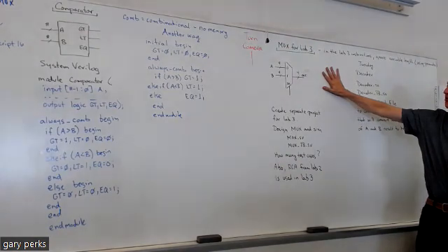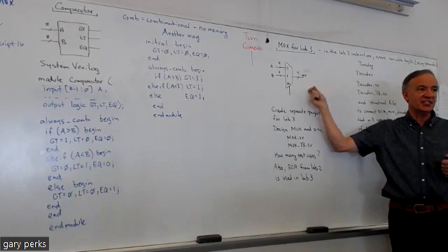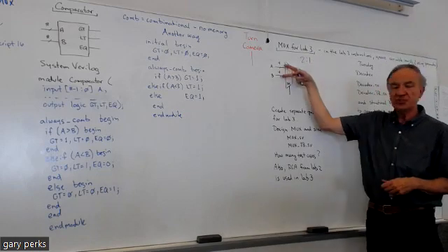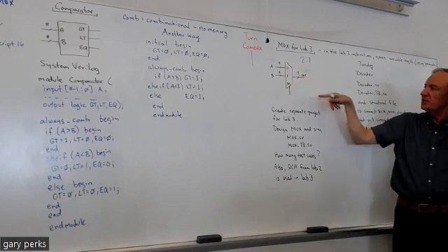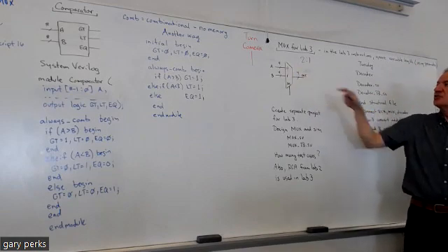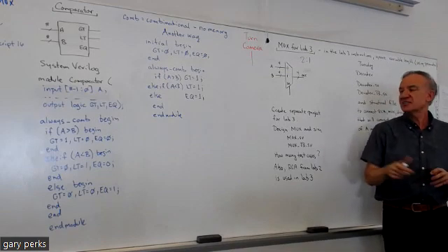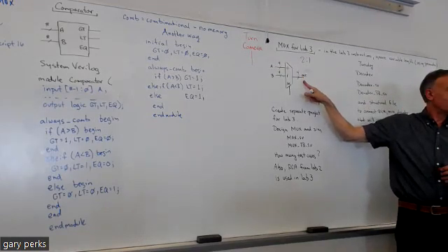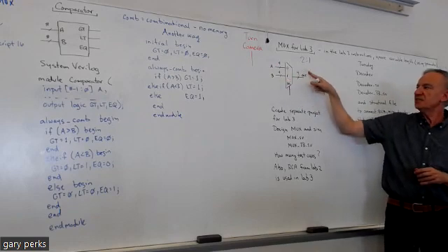So part 2 of lab 3 is design this mux and test it, right? Simulate. So this is a 2-to-1 mux. See, there's only 2 inputs. Again, muxes always have just 1 output. Each input and each output has 4 bits. So since I only have 2 data inputs, how many bits for my select? Just 1, right? Because if select is a 0, data A will be connected to the output. If select is 1, data B will be connected to the output.